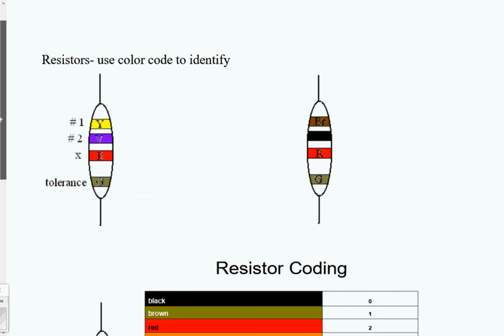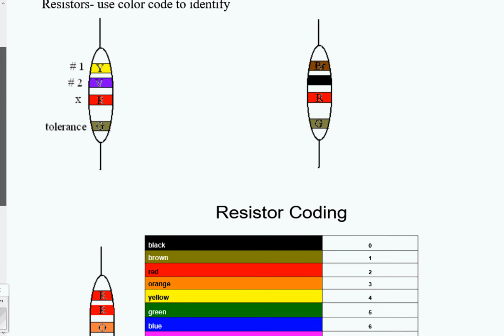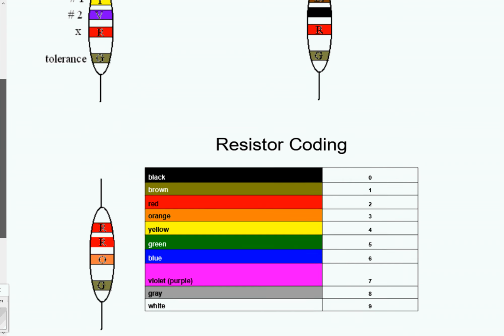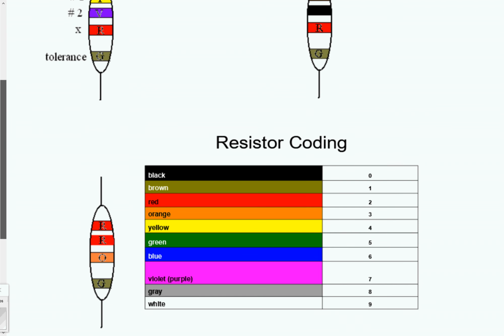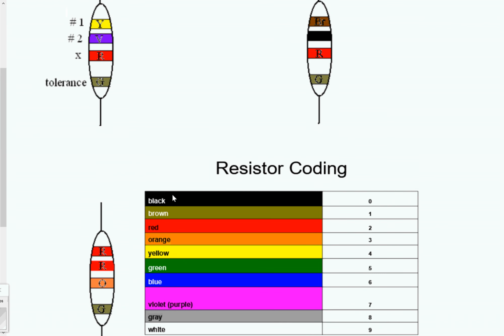Now, this is going to be a 30-second crash course in reading resistors. So all you need is this color code that you see in front of us. Here's the color code that we have, and this tells us everything that we need to know about a resistor. Remember I told you gold and silver, that's always the last band. That's your tolerance band, your fourth. So look at this resistor: yellow, violet, and red. And what it tells me is this.